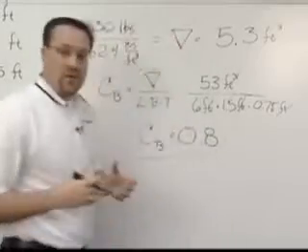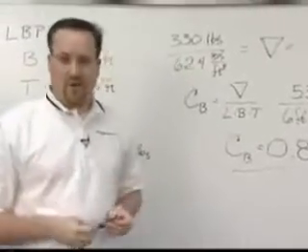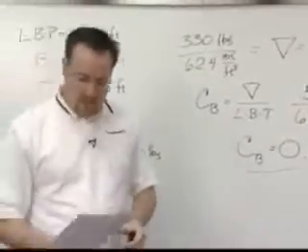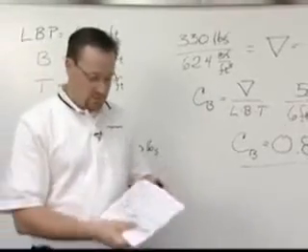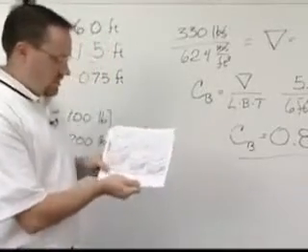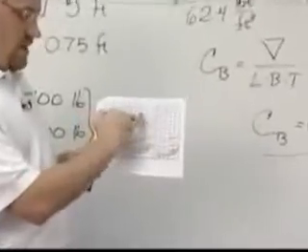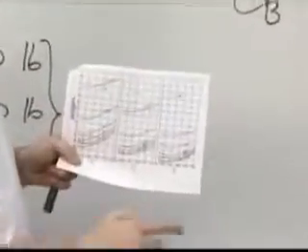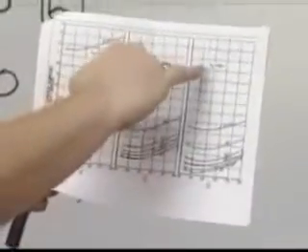And this is going to be important for the next step. Okay? The next step, as I would do it if I were doing this calculation, is to look at this series of plots. We call them nomographs. All right? You have a copy of these in your guidelines. You'll see that here we have 3, and they are for different block coefficients. We know what our block coefficient is for this design. It's 0.8. So we'll look at the plot that's representative for 0.8.